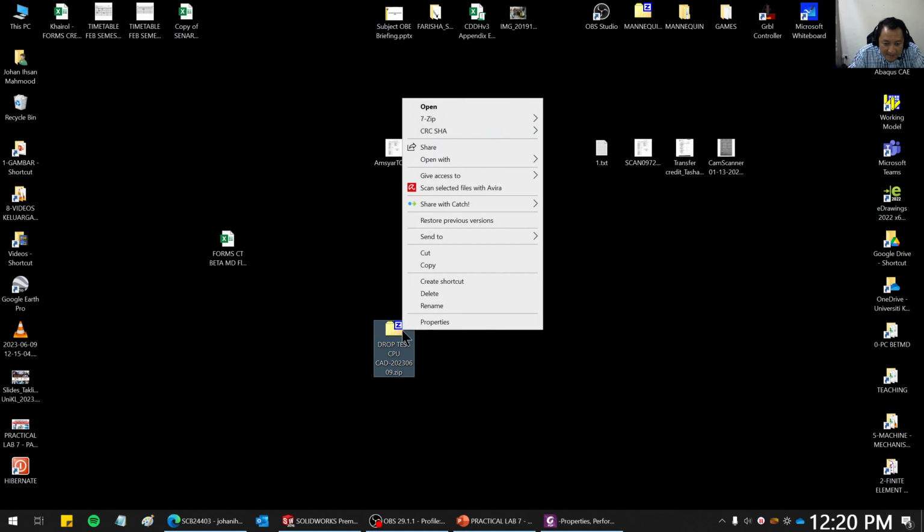Do you want to go in that way or do you want to flip? Can I flip it? I can flip it like that. Okay, so that's 45. So I can click OK. So I've got a drop plane. So later when we set it to be dropped, it will drop like that. So there is no need for you to rotate your component. You just have to rotate your plane.